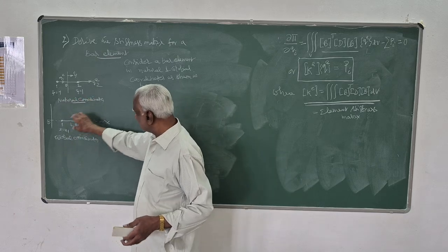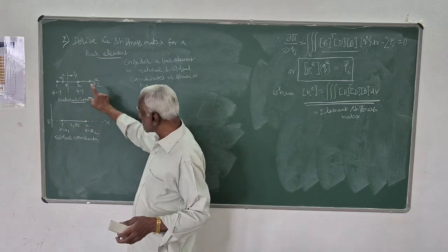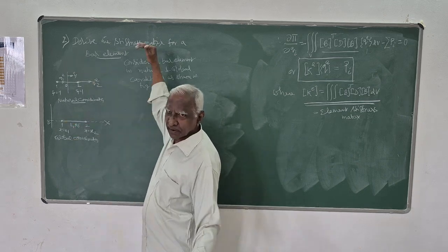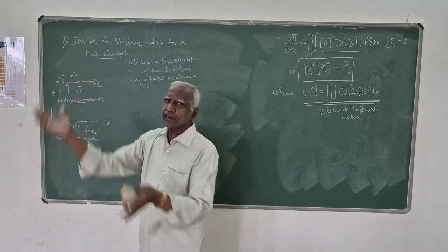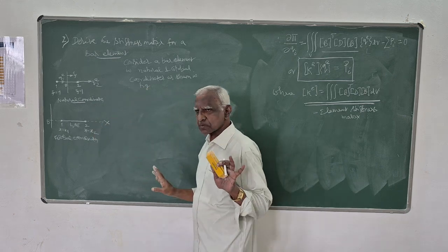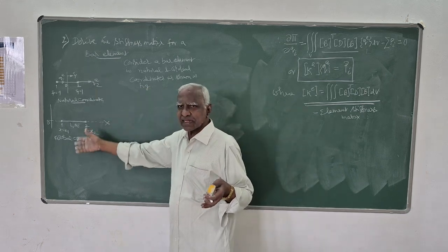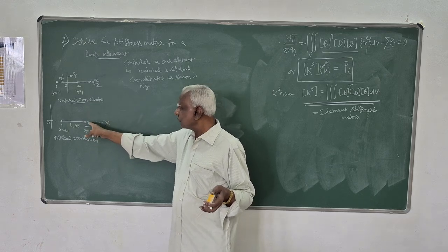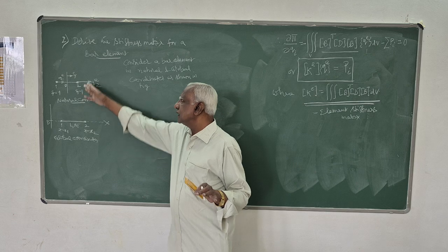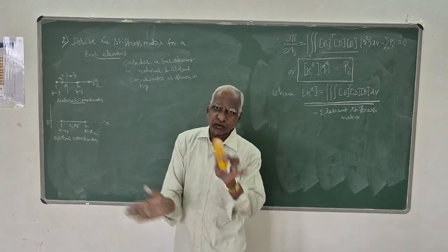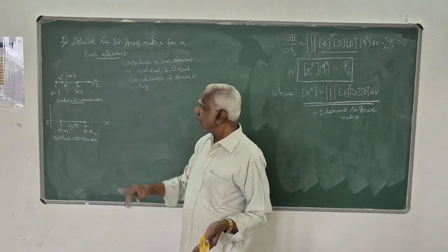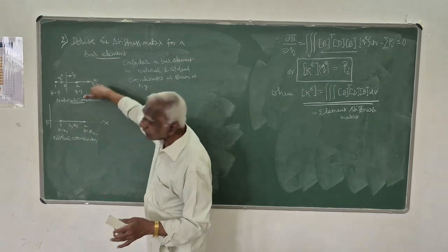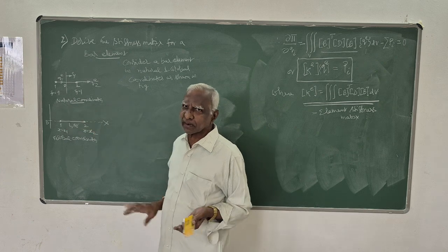Strictly speaking, in the global coordinate, by assuming this as an isoparametric element, we can assume any arbitrary shape. It can incline in any fashion in space. But I am writing it in the same line. If you map it for a first order bar element, it is of the same shape. It is not going to change its shape. Whereas if it is a 3-noded one, then it will assume a curved shape in the isoparametric formulation.